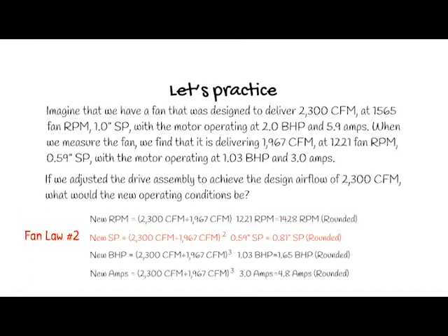Next, we looked at static pressure. For static pressure, we had to use fan law 2. Again, we took 2300 CFM divided by 1,967 CFM, and then we squared it. We took that number and multiply it by the original static pressure of 0.59, which gives us 0.81 static pressure.